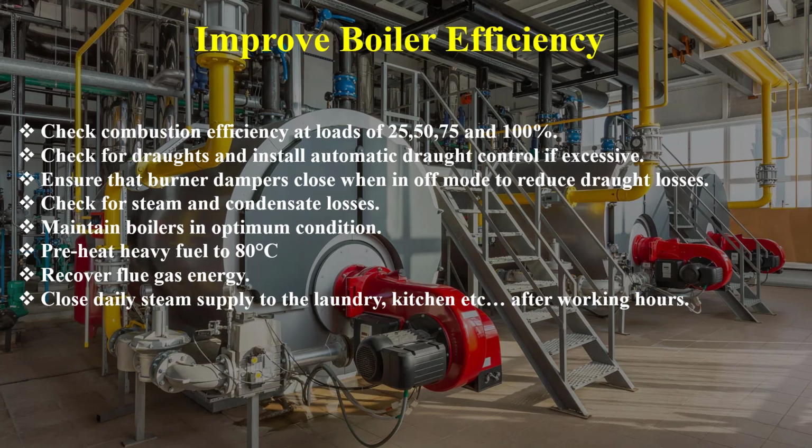Improve boiler efficiency. Check combustion efficiency at loads of 25, 50, 75, and 100%. Check for drafts and install automatic draft control if excessive. Ensure that burner dampers close when in off mode to reduce draft losses.